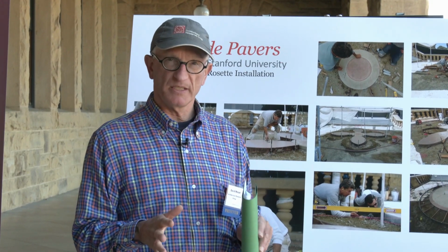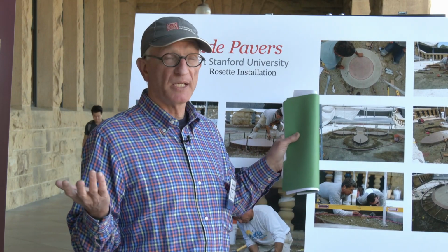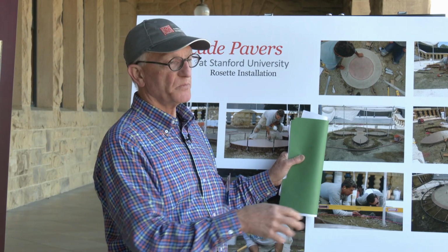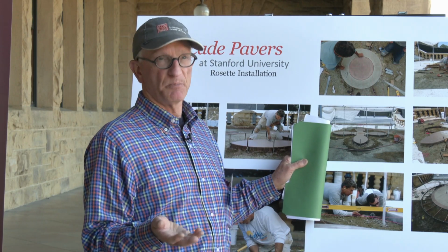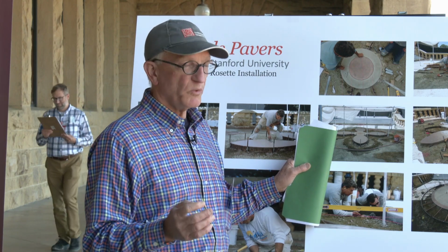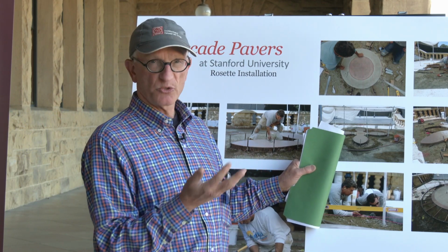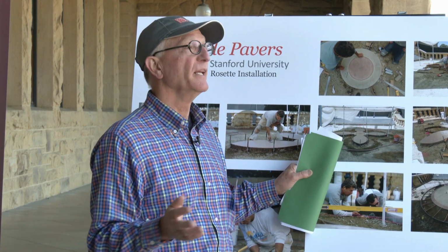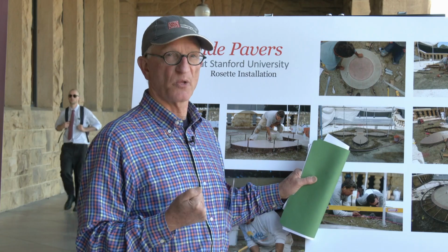We add a pigment that is a mineral oxide, so it comes from the ground. And we did make a mistake one time. We lost the supplier for one of our mineral pigments. We ended up trying to use a liquid pigment, and that did not produce the right color. And we had to replace those pavers. So what we found in this particular type of work on reproducing historic fabric is that going back and doing exactly the way it was originally is the way to match for the whole quad, so there's not an inconsistency.